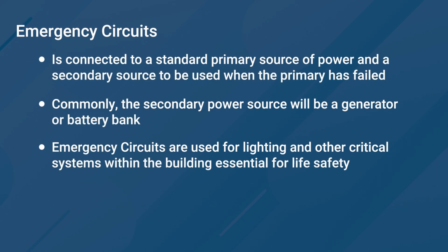Emergency power systems are in place in most industrial, commercial, and some residential systems. These provide a secondary source of power to take over certain circuits in the case of a power failure, when the electricity on the primary source is disrupted for a period of time. Emergency transfer panels will switch over circuits from the primary system to a secondary generator or battery bank in this case. Emergency circuits that would be connected to this system may include selected lighting fixtures, fire and safety systems, and elevators.